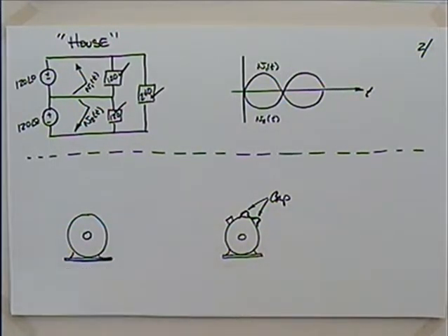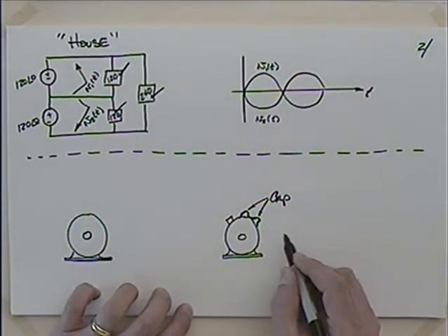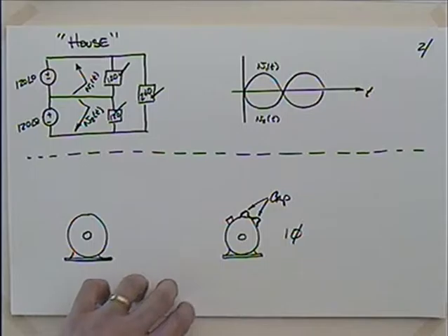And there might be, just for startup, sometimes they'll be on a centrifugal switch and you'll actually hear it as it gets up to speed. You'll hear a switch go in or out, and it uses those for starting. Sometimes it'll use capacitors for running. We talk about starting capacitors and running capacitors. That is very indicative of a lot of single-phase motors.